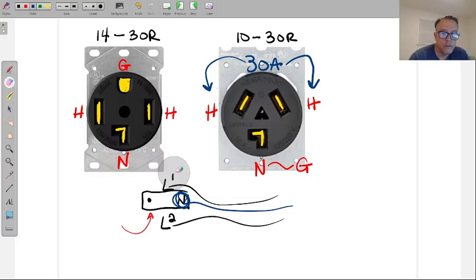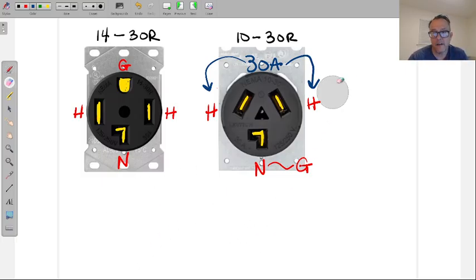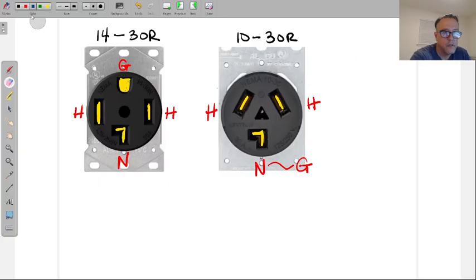So if you run into that situation, now you have at least some idea that you don't have to panic. Maybe you didn't remember all of that, but some idea that, oh, this is something that I can do. But if you remember nothing else, just remember this: don't change the outlet, change the cord to the 3-wire. And then from there you can go forward and try to find if you still need to see the configurations and all that.